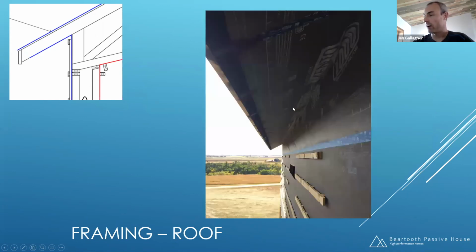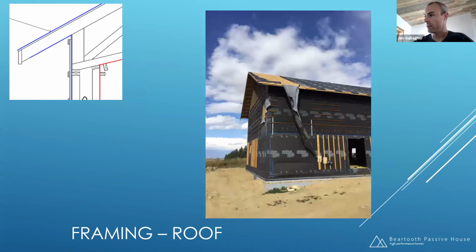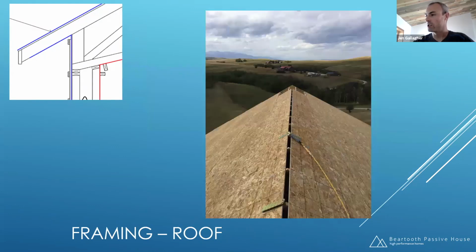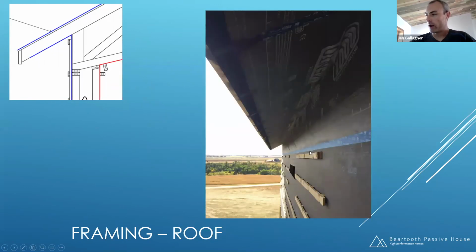Aaron, I think, actually, I'm gonna step back a couple. Okay, so we've got a vented attic, right? So all my air is coming out of this little gap here in my ridge vent. We've got a rain screen. So once we get siding on here, you're gonna have hot air coming up the backside of your siding. And there are, I think, different interpretations of what is the best practice.